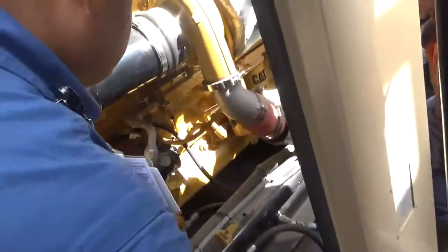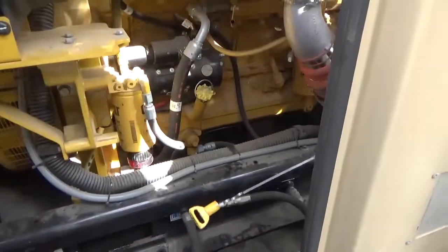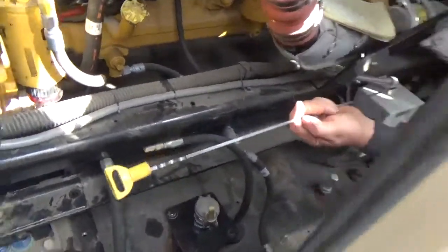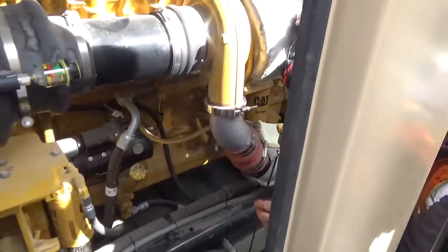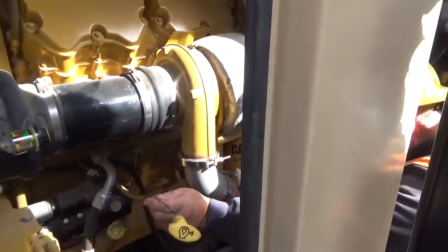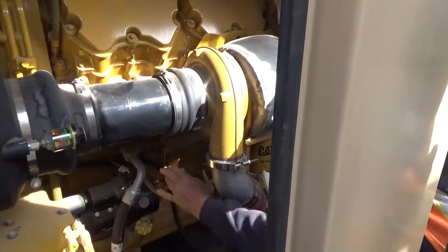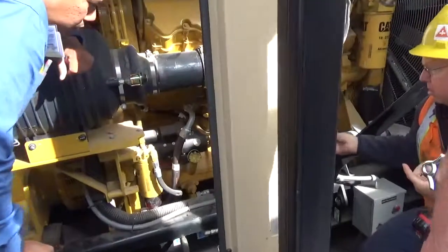So it has 2 sides of the stick. Just make sure you look at the right side. One says engine stopped, and the other says low idle, but you can check it at rated speed. So that way, at least when it's running, if you're in a prolonged outage, you can come up because it is going to use oil at no load. If your load is really light, it is going to use oil. It's just a function of it because the rings aren't seated. So at least you can check it, and then you can add it while it's running to bring it back up to the full mark. Yeah, what type of oil?